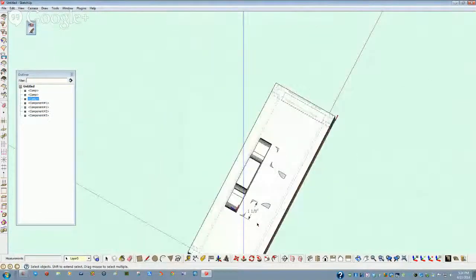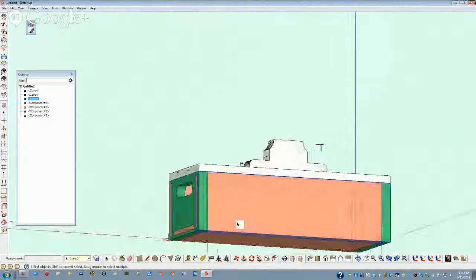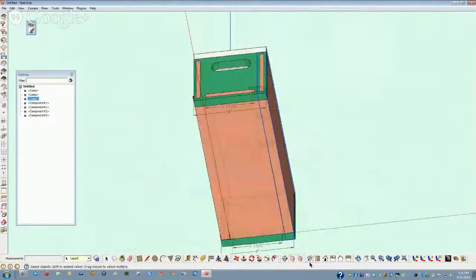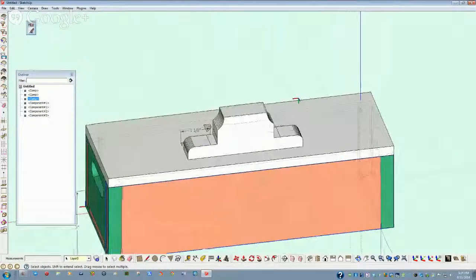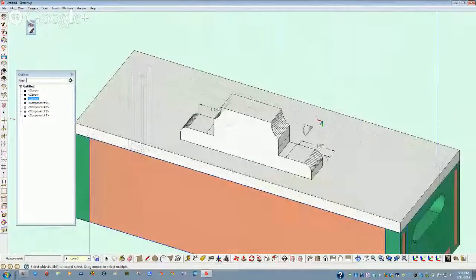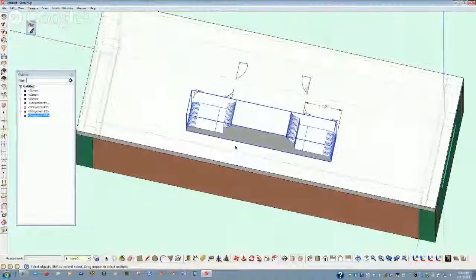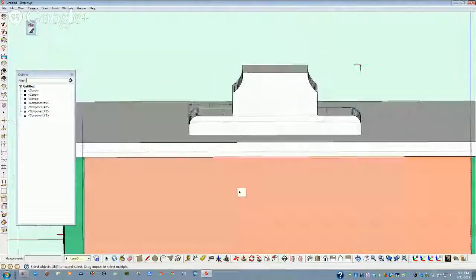Now it's not in the center. You can go ahead and center it. Put it diagonal if you want to. Let's go back to an ISO view here. Don't like an ISO from the bottom up. It did not get my fillets here, which is okay as far as I'm concerned right now. It's showing what I want to do. It didn't get it because I didn't get rid of those two elements right there when I made my component.